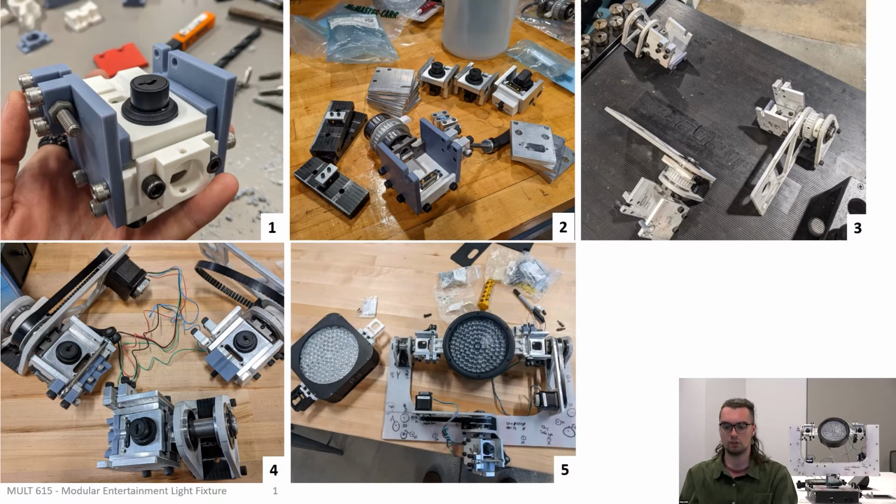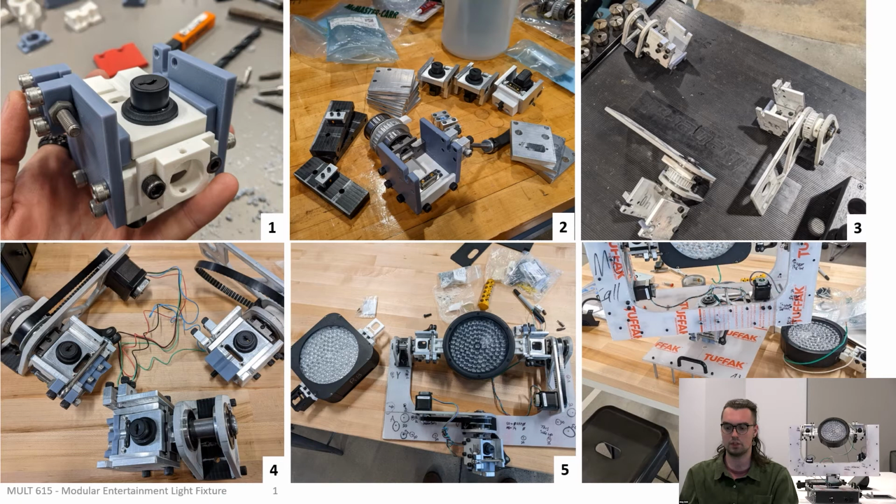Initially, in the joint, high current blade style Molex connectors were the core of our design. However, those products had limited availability due to COVID, which required them to be substituted for lower pin count, but equally mechanically and electrically robust D-sub style connectors designed for high DC currents drawn by the motors and the head units. We had to design our light joint around these products. For precise motion and holding position, the drive system needed to move cleanly without jerking or bouncing and hold precise positions when at rest. For this motion, the joints are driven by trapezoidal profile belts and pulleys, powered by stepper motors with encoders for position feedback, which is a common solution to this problem in industry.